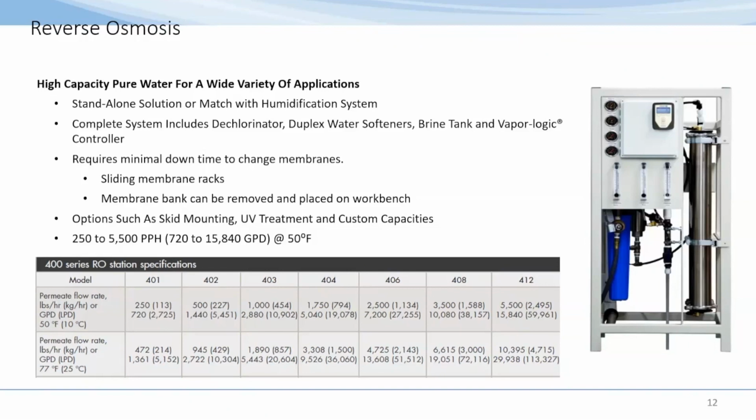The second thing is you're removing that risk of heating it to a zone where bacteria and viruses thrive at 77F and above. Obviously not all the way to boiling. So with that, when we look at these systems and they're sized for 50F, knowing the water coming out of your ground, you'll meet that capacity that's listed versus having that surprise of potentially not having enough.